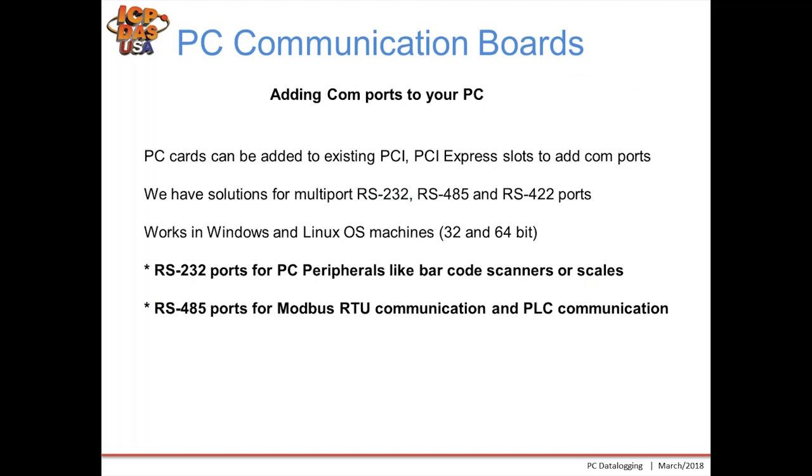And these can be used to communicate to peripherals like barcode scanners and scales via RS-232, and are especially popular for using with our data acquisition equipment for Modbus RTU communication and PLC communication. Other applications are like configuring PLCs or talking to HMIs.